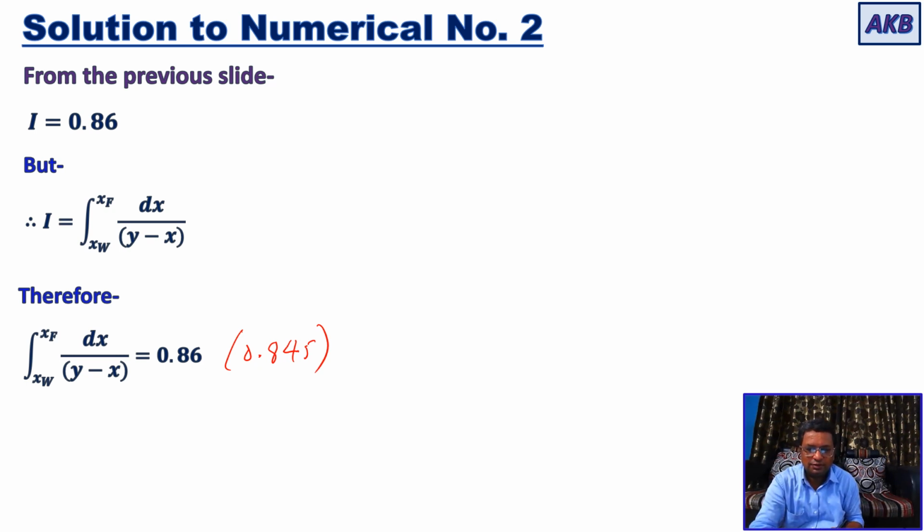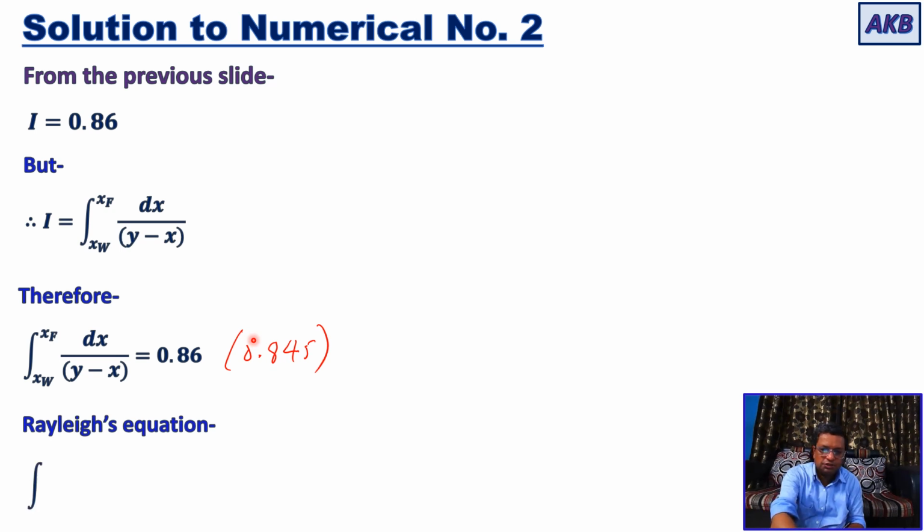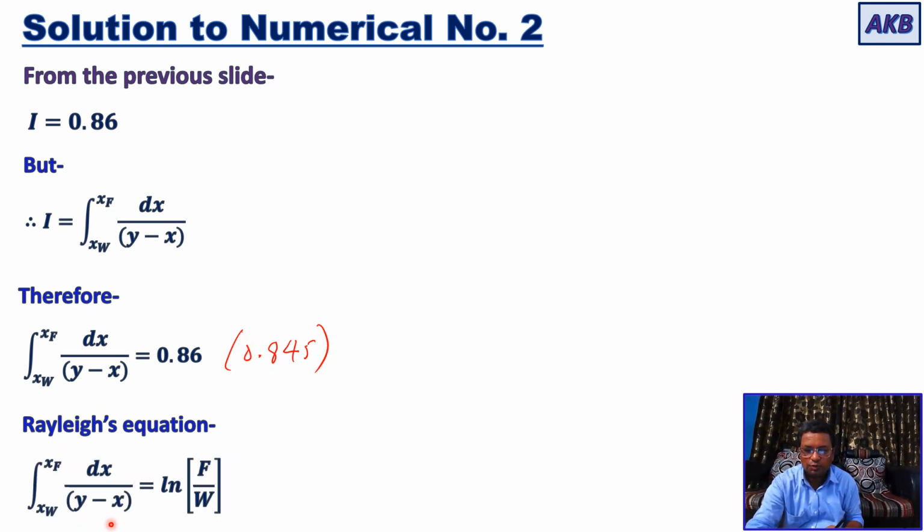There I have solved this integral graphically, and the value obtained at that time was 0.845, and analytically we are getting it as 0.86. So Rayleigh's equation is integration from xw to xf of dx upon y minus x, that is equal to ln of F by W.